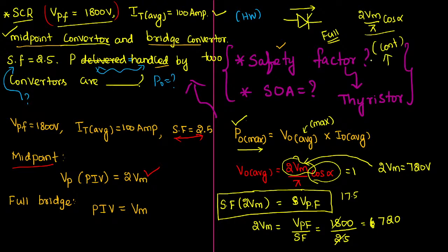In the given question, if there is no information about the type of the load that they are connecting, then by default you can assume that the converter is producing continuous load. It means your output current will be ripple free. When there is no information about the output current, you can assume that the current is always continuous on the output side and it is ripple free.